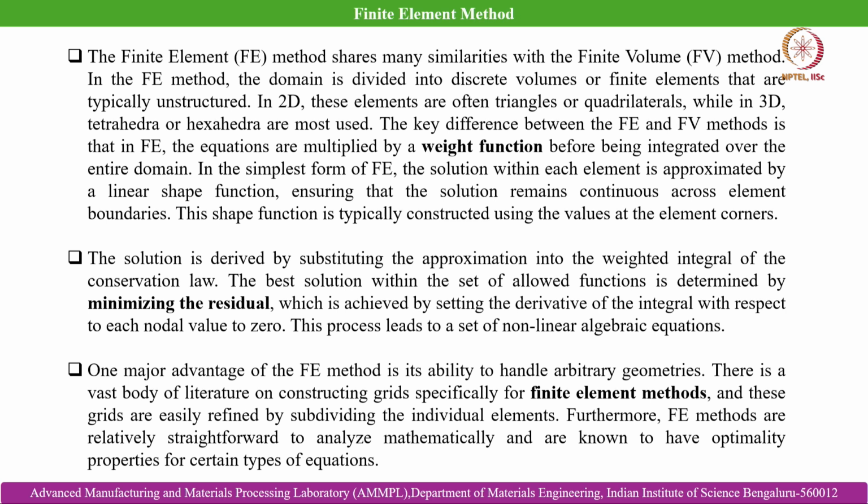The finite element method shares many similarities with the finite volume method. In the FE method, the domain is divided into discrete volumes or finite elements that are typically unstructured in 2D. Here, the key difference between finite element and finite volume is that in finite element, the equations are multiplied by a weight function before being integrated over the entire domain.